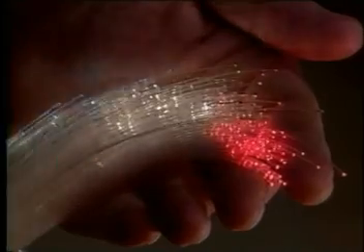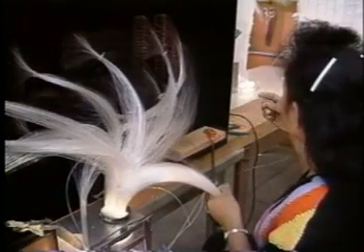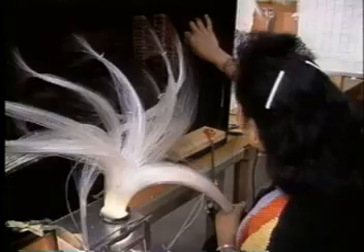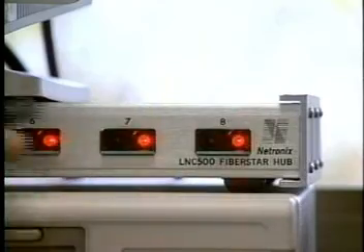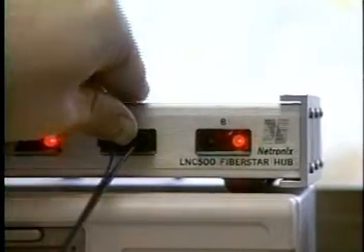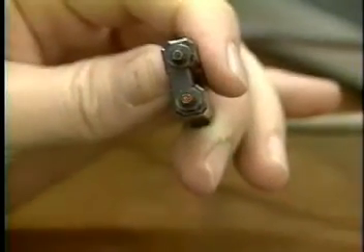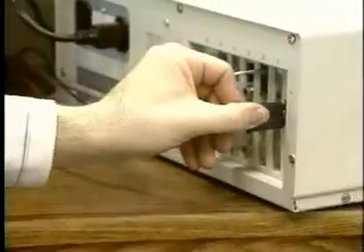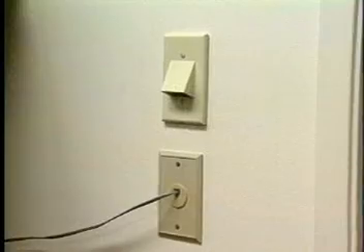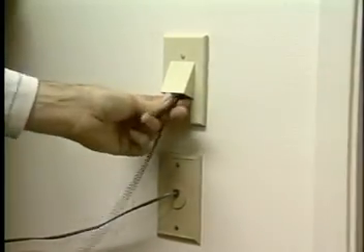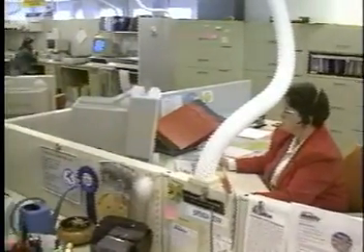Fibers with large core sizes can handle larger light volumes, higher optical power levels, and are convenient for use in fiber optic signs and the delivery of laser beams for surgical or industrial applications. Fibers can also be made from plastic materials, offering low cost and ease of use. Today, 1000 micron plastic fiber with a 980 micron core is well entrenched in lighting, signage, and automotive applications. It is now becoming a serious competitor to Category 5 UTP wiring, providing an optical alternative for short-distance networks.